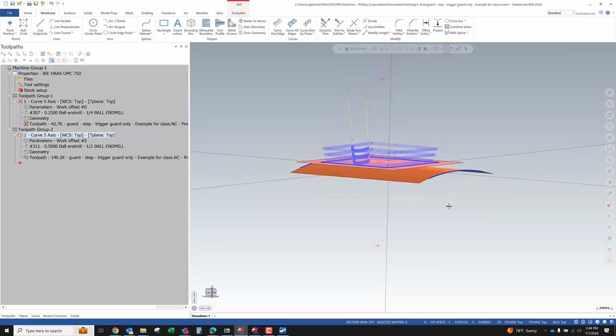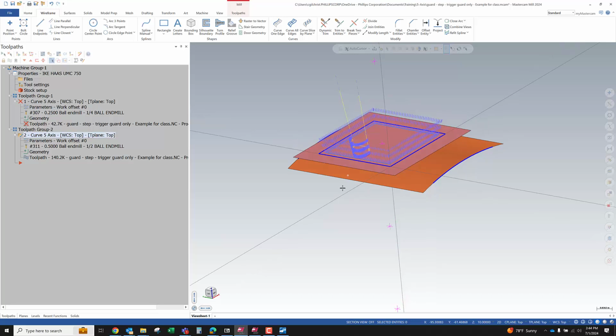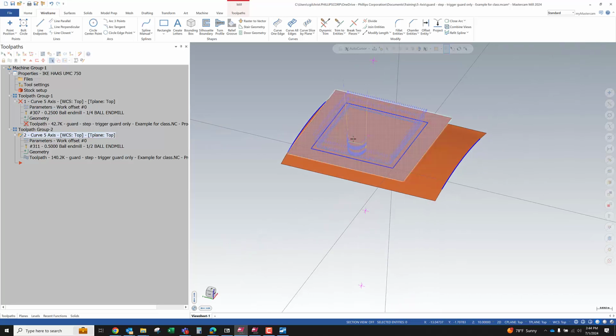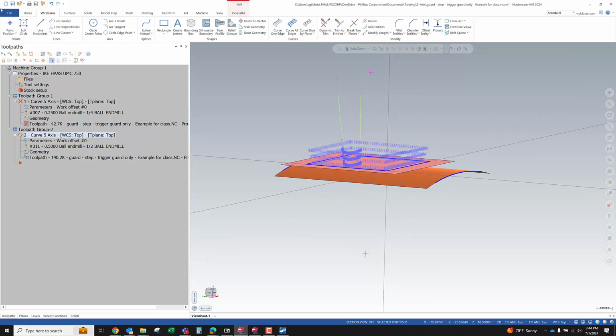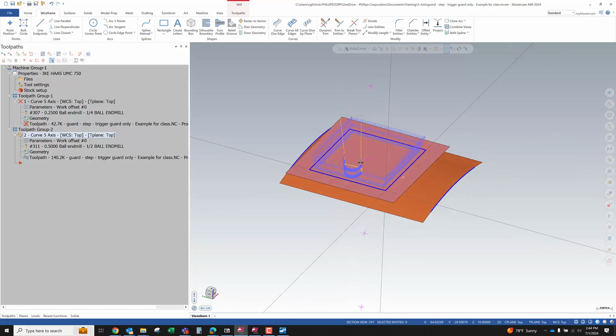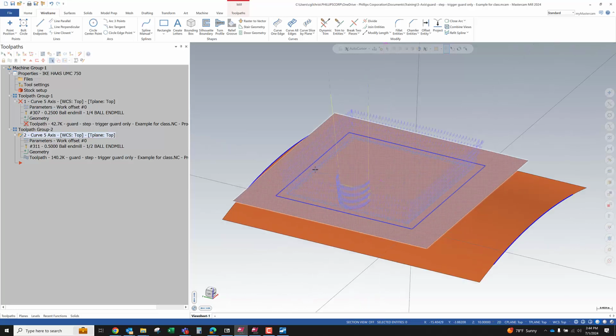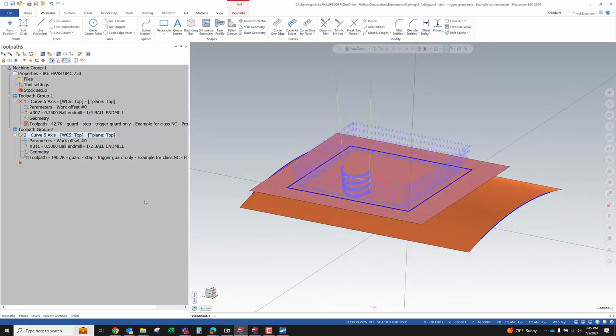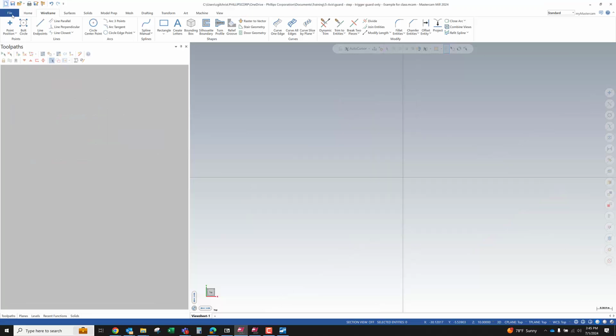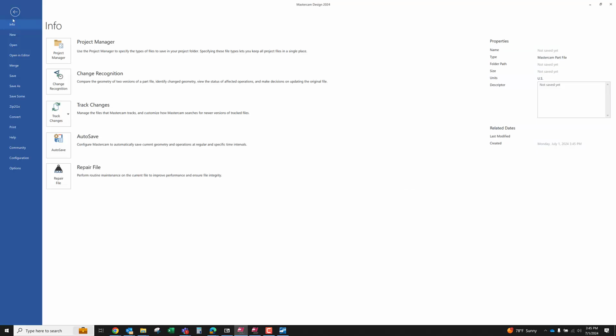The last example is chain, as I'm sure you can probably guess. It allows you to use a chain up above the toolpath or below the toolpath to constrain where it can go. Can be pretty useful. Quick example.